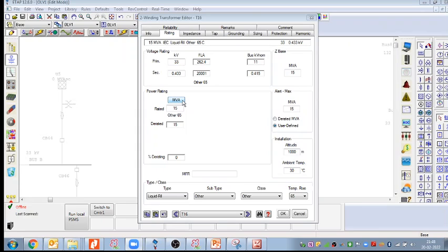Okay, so 15 MVA we cannot take, right? So what can we take? Mostly, generally, what we take. I have received some correct replies also. Yes, 2.5 or 5 MVA. Correct, Sanket. Generally we go with 2.5 or 3 MVA. Let us take 3 MVA.